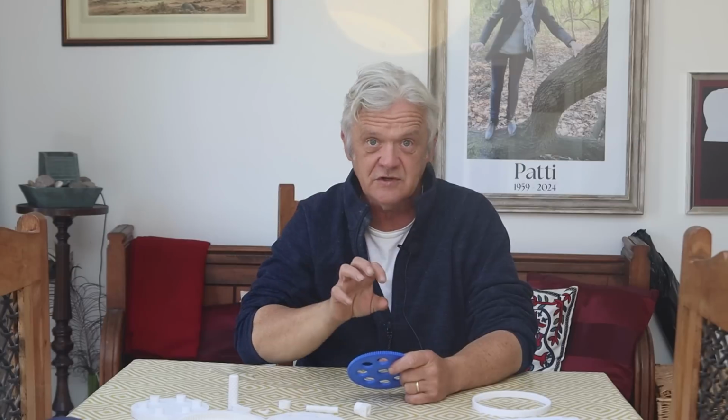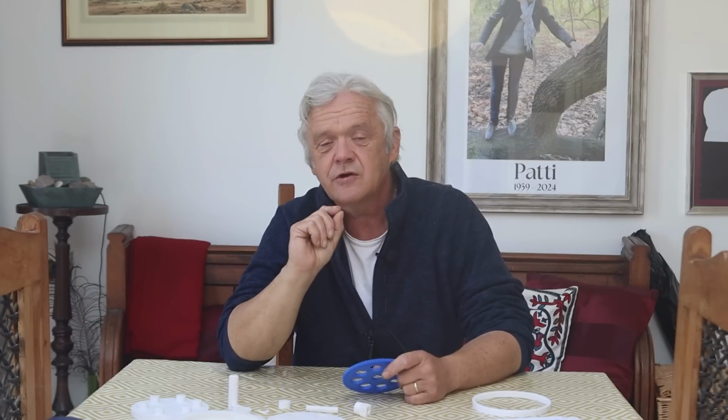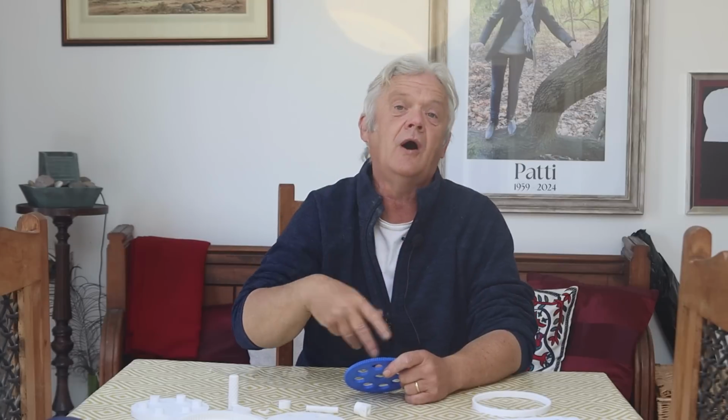But it is a bit frustrating when you're first picking it up, trying to find out where on earth you haven't put a constraint and it's telling you to put a constraint. So the idea would be, don't bung all of your drawings on at once and then try to constrain them, because honestly you'll just get lost. Add the elements to your sketch as you go along and make sure they're constrained as you add them, and then you'll find that the whole sketch becomes fully constrained.